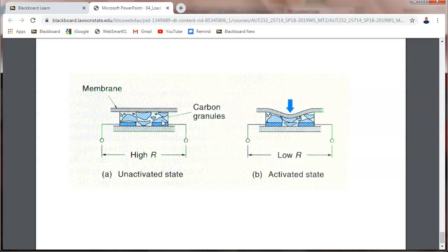We use it on a lot of iPads. The problem with the ones on your cell phones is that these are what we call capacitive sensors. If I put the gloves on, what happens? It can't work anymore. So most iPads we have out in the industry, the human machine interface displays, work on this principle right here. You come up here and you actually have to press on them, and what you're doing is generating a change in resistance in the center.